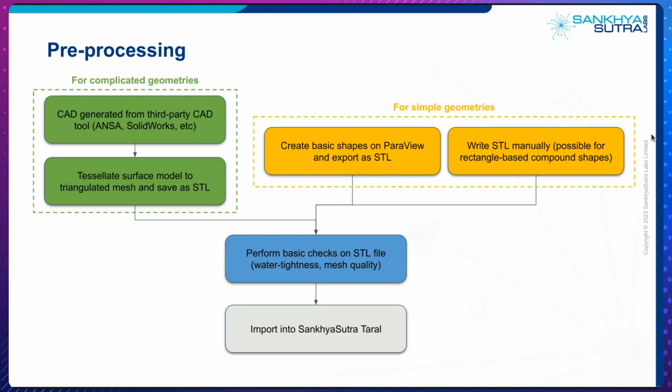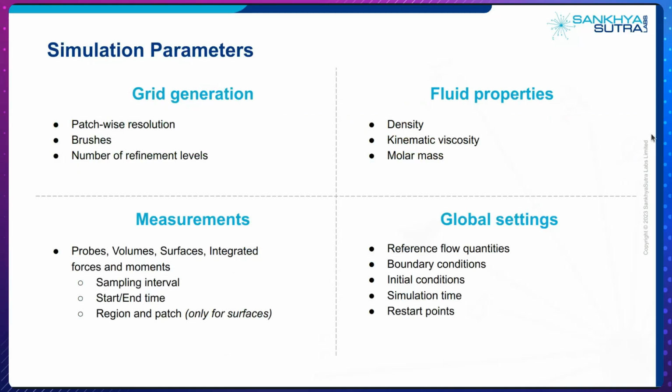So once you're ready with the STL file, you can import it, and a few checks will be done by the solver itself to ensure that the geometry is watertight and that the mesh quality is sufficient or satisfactory. And once this is done, you can proceed to the setup of your case. So in terms of case setup, we have four broad categories. The first is to input all the parameters that are related to grid generation.